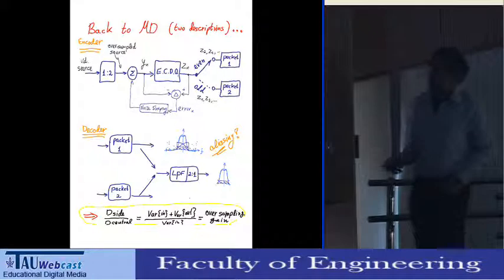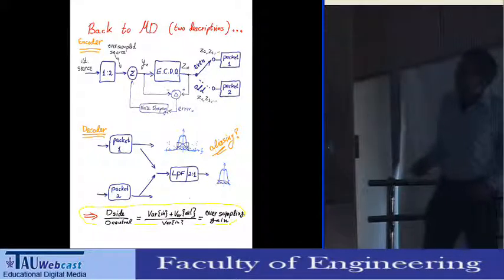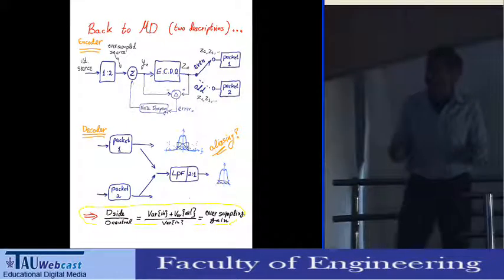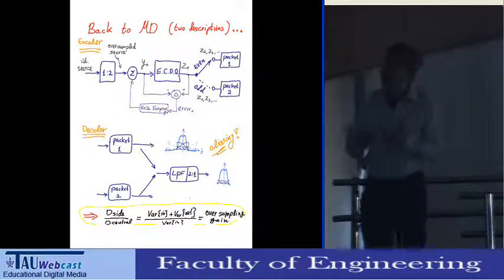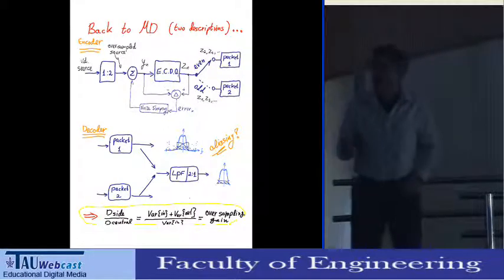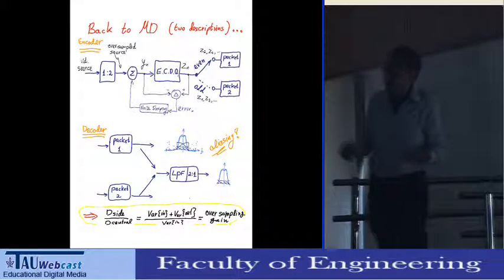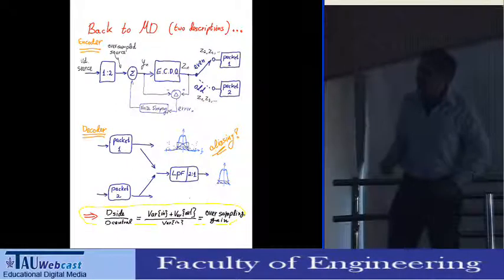And okay, this is the usual delta sigma, basically. But now I need to build two packets from the oversampled source. So I'm doing it in a simple way. I'm taking the even samples, putting them in one packet, and the odd samples in the other packet. Since I oversampled by a factor of 2, each subsequence is good enough for the source if we didn't have noise, of course. That's Nyquist sampling. And if I get both packets, if I wouldn't have noise, then I don't need it.